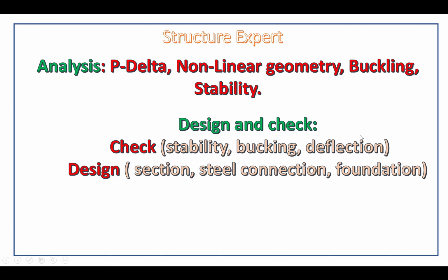This is pretty important. And for other phenomena like resonance or like vibration, we do not concern about it, because no people live at that board. So that board we use only for the advertising, so not affect on the human. If this structure affect on human, you have to check another criteria, okay, to make sure the human can live on that location. And for design, we design section, stick connection, and foundation.